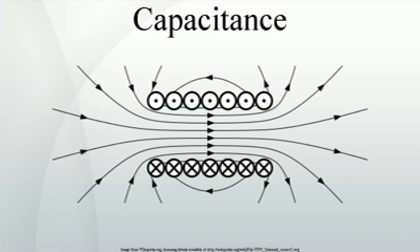Example values of self-capacitance are: for the top plate of a Van de Graaff generator, typically a sphere 20 cm in radius, 22.24 picofarads; the planet Earth, about 710 microfarads. The interwinding capacitance of a coil, which changes its impedance at high frequencies and gives rise to parallel resonance, is variously called self-capacitance, stray capacitance, or parasitic capacitance.